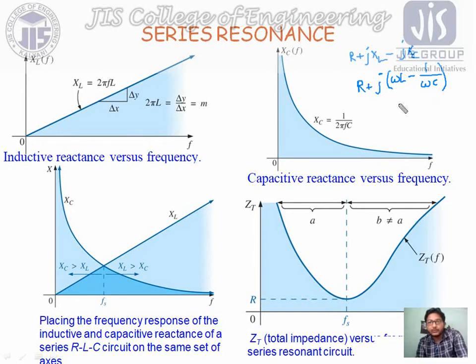Now for this case, this was the overall impedance, that is our Z. So for resonance or any other condition, our current I equals V by Z, obviously, which we have already calculated. If our supply voltage is fixed and we are only changing the frequency, then based on this Z, our I will change. And the voltage across the resistance, VR, will obviously be this I into R.